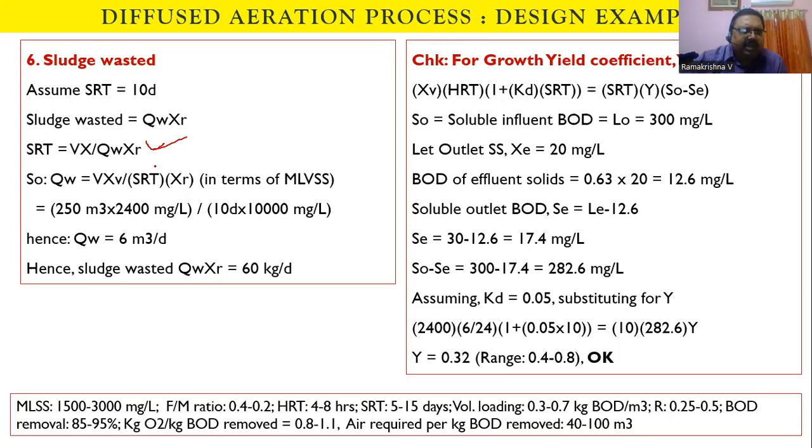So SRT we have to assume here. The SRT value in the design is given as 5 to 15 days. So I'm assuming 10 days here.